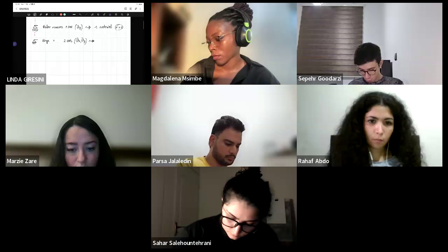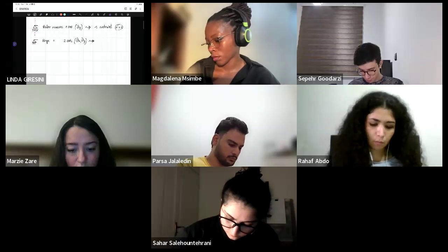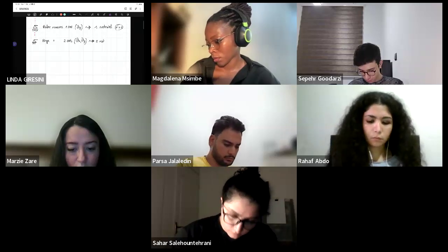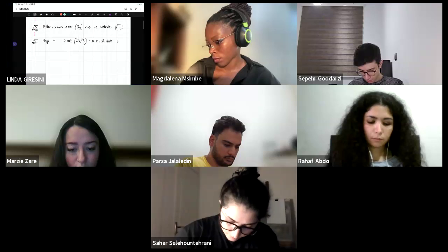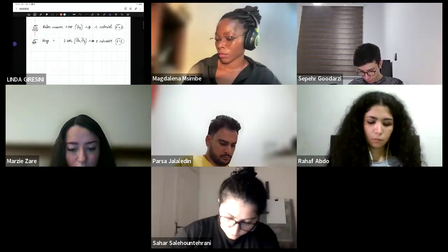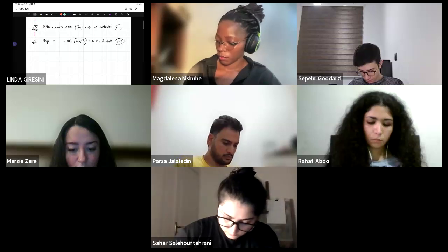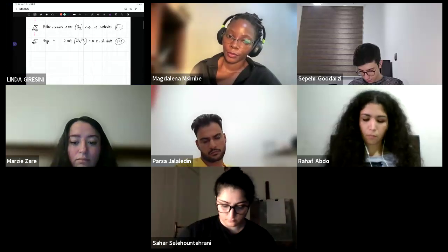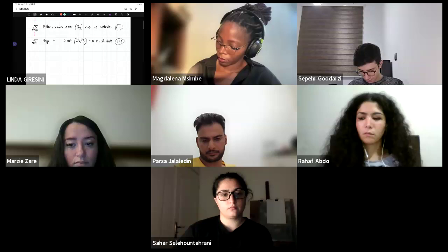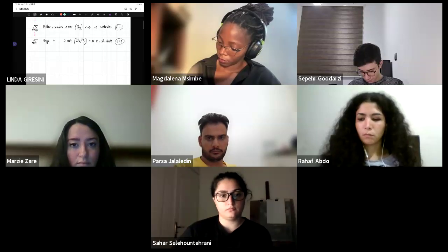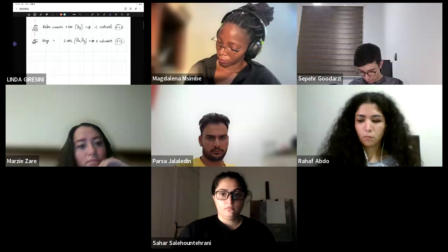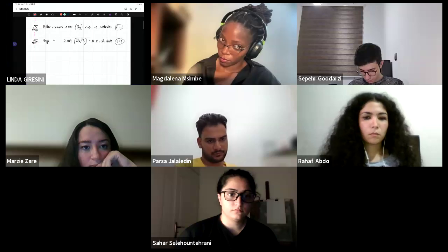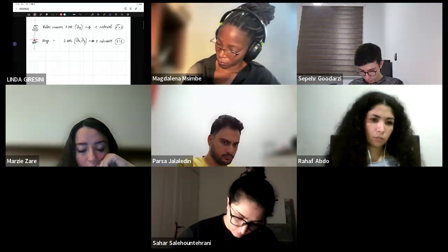So how many restraints do we have? 2. So R is equal to 2. Because vertical translation and horizontal translation are blocked. It cannot move. That point must be fixed there. It can only rotate. So the lines of action are horizontal and vertical. They are 2 now.